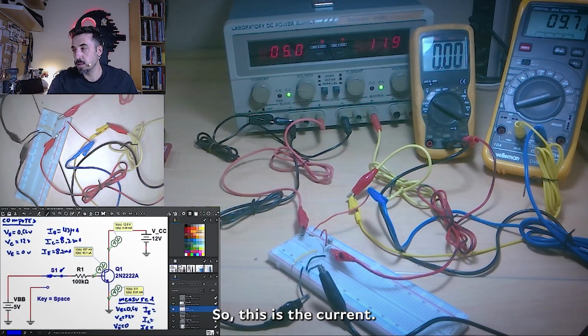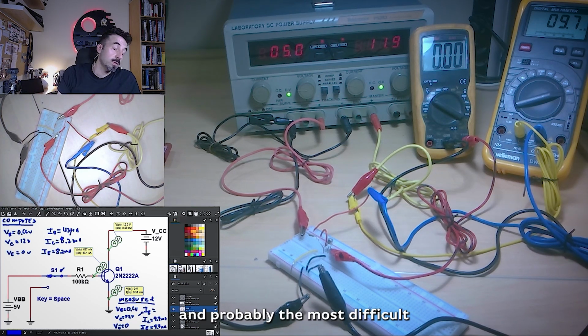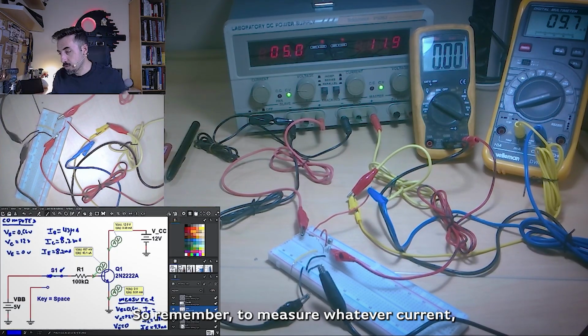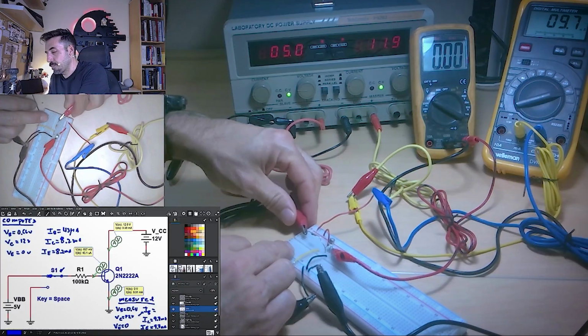So this is the current, it's connected there to the collector, and we have 9.7 milliamps, which is the typical thing. I'm not going to do it because the important one here, and probably the most difficult one to measure when you have to do some kind of measurement with a bipolar transistor, is to measure the current through the base. So remember, to measure whatever current, first thing that you have to do is to break the circuit.